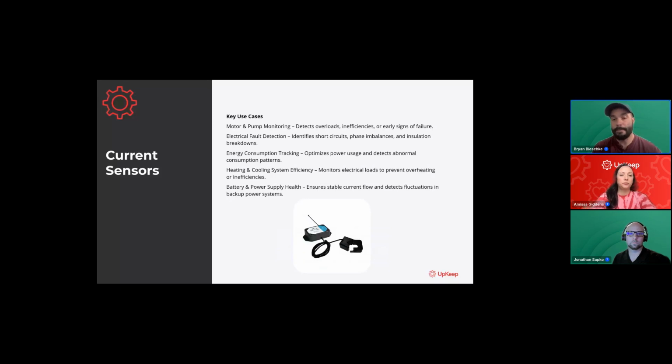Current, again, right? Current is great for on-off monitoring if you want to measure the cycle and run times of electrical components and machinery. You can detect faults, right? If we have overload faults on machines, or trip-outs on motors or compressors or anything like that. Electrical loads are monitored everywhere, and it's extremely valuable.